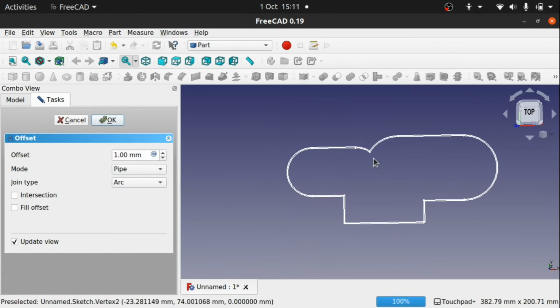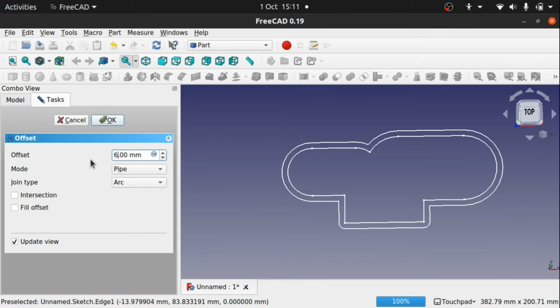and you can see we've got an outline that's happening here. So we can send it outwards. I'm going to send it outward by 6, and we'll create this outline that goes around here. You can see some of these edges are curved here, and that's because we've got this arc on. Set this to tangent. That actually sets those sharp edges there, which have been done by the square, as a tangent. So a tangent means touching, and those will be touching there.